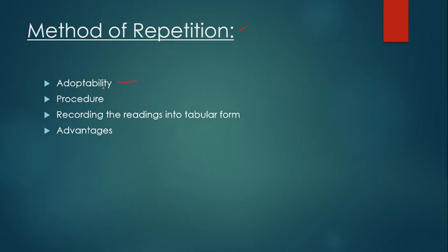Our instrument has a least count of 20 seconds, and some other instruments may have a 10 seconds least count also. So in order to find an angle below 20 seconds, let us say about 10 seconds or so, we can go for this method, that is adaptability.